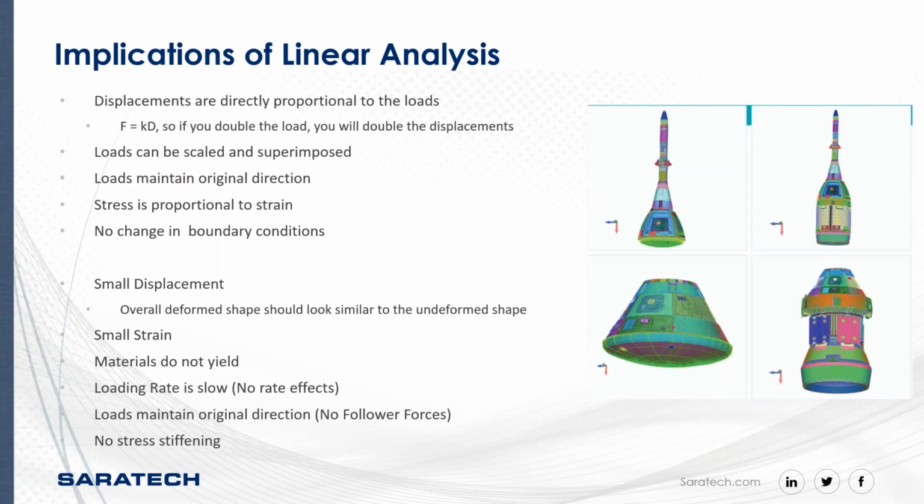So here are some implications of a linear analysis. Some of these things are useful, and some of these things might be detrimental to your solution. Force is equal to the stiffness times the displacement. The nice thing is, if you are in a linear realm, you can just scale and superimpose loads instead of running different loads. So if you have a 1G load case, it's easy to scale that 1G load case into different G load cases instead of resolving the model.